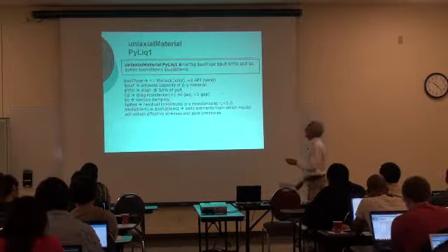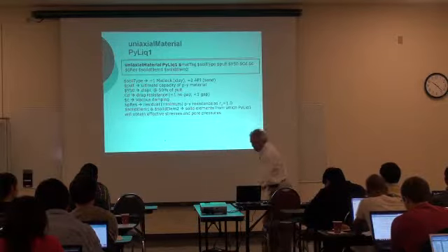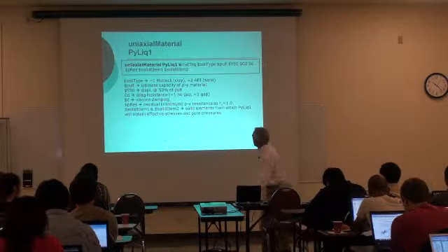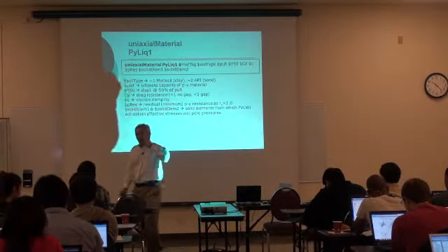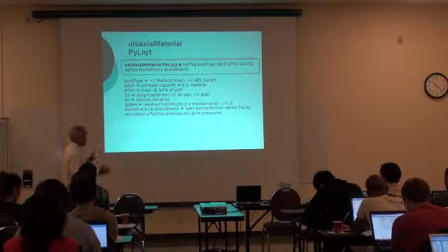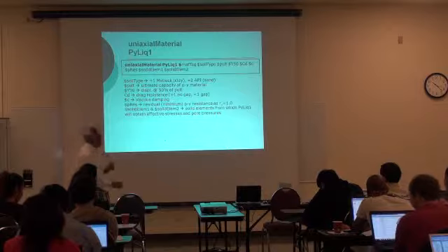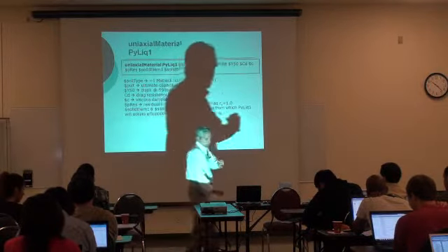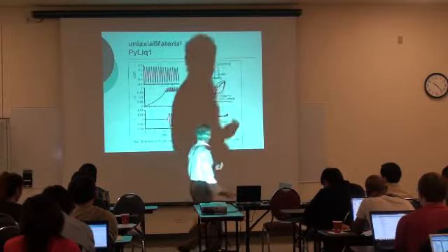And when you have a liquefaction, there is also a little spring that is specific for those situations that allows you to consider the degradation of the stiffness and the P ultimate, in particular the P ultimate, as the pore water pressures increase. And it's based on what is called the pore water pressure ratio. So when the pore water pressure ratio goes close to 1, then the P ultimate goes to 0.